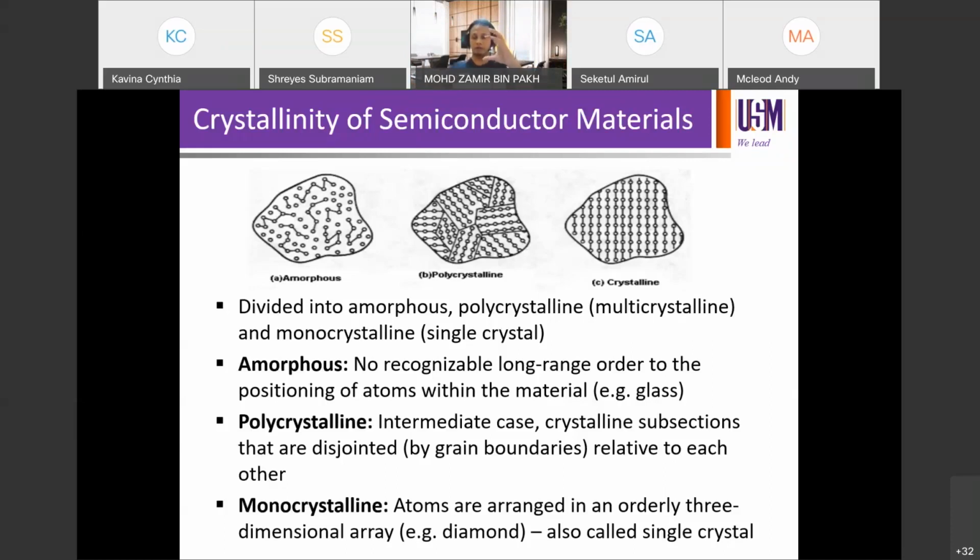You can see them by using naked eyes, because some grains are really small that you have to go down to the microscope or SEM or some other tools in order to see the arrangement to some extent. Some you may not be able to see at all. You might have to do XRD to see a couple of peaks to see the presence of the different grains. And for monocrystalline, usually you can see by naked eyes, by the color, usually. We can relate later on, okay?